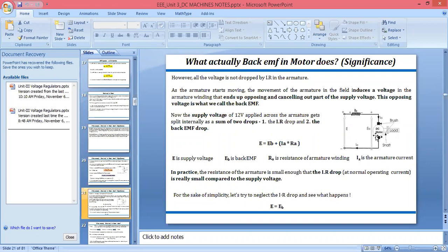So accordingly, KVL means Kirchhoff voltage law. Kirchhoff voltage law states that the algebraic summation of the potential drops or voltages for a closed loop will be zero. So if there is a supply voltage, a battery, and you see the summation of the voltage for this loop, that will be zero. And you will take the direction according to the sign convention. So if you calculate total EMF, total voltage, that will be E. E equal to back EMF plus the drop across the resistance, which is given, and we can calculate the value of current. So that drop will be I into RA.